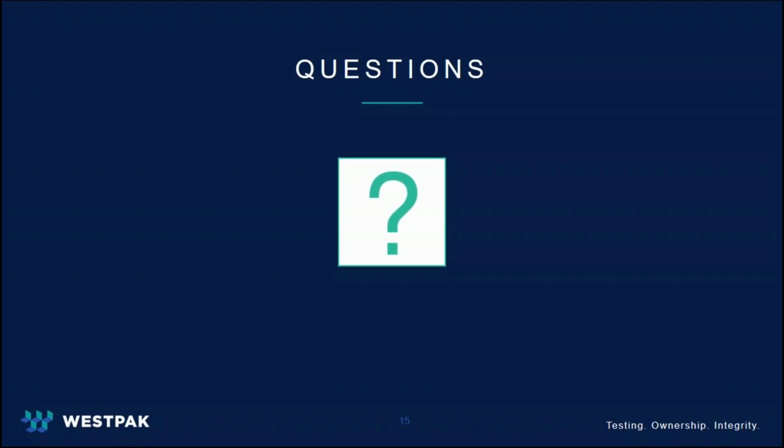So what's our next question? Okay, cool. Greg, there's a question about gross leak detection. Are there patches or stickers you can attach to problem areas, such as a common pinhole area? I wouldn't recommend putting patches or stickers over the leak, because if it's a leak in your poly side of your pouch, that could cause additional failures and it may have microbes get in through that same pinhole. I'd recommend changing the configuration of your package inside the pouch or tray to make sure that you don't get punctures from the inside out.